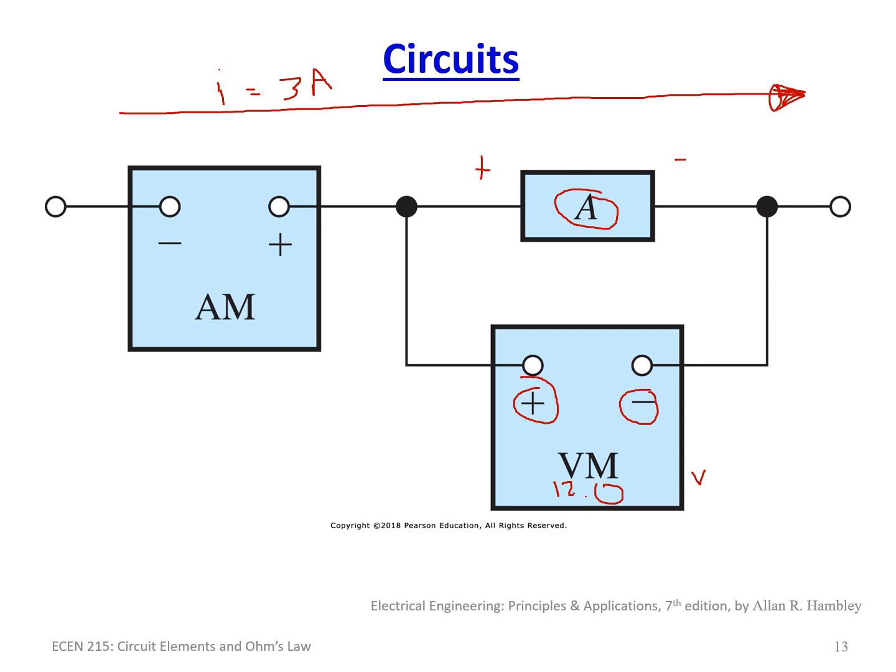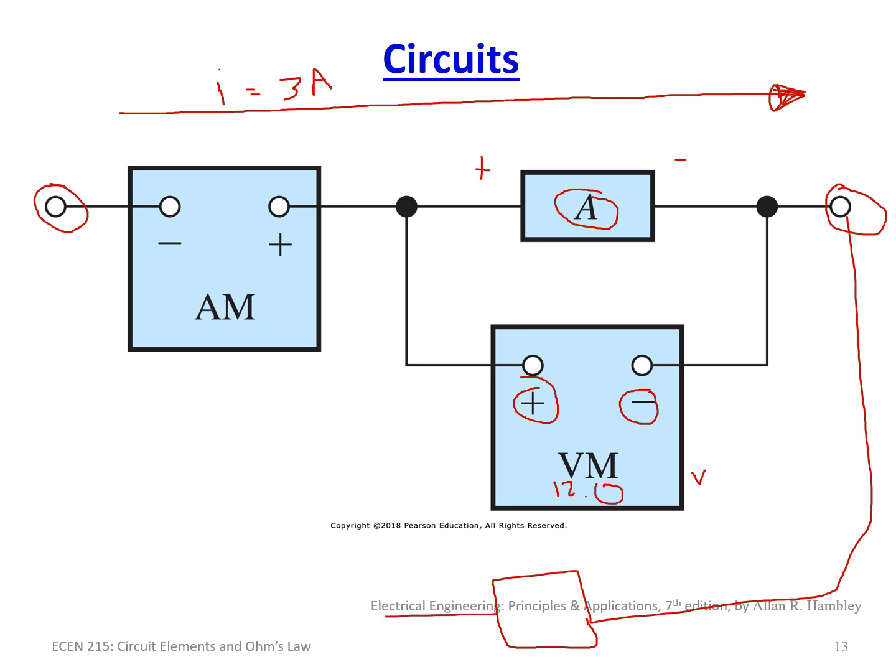If we have 3 amps going through here, through some sort of unknown thing that is connected here, whether a power supply or whatever it may be, there's some other circuit element here that is unknown. We'll just draw it as a box and put a question mark in it for right now. So we have some sort of device, a power supply, driving this current of 3 amps through circuit element A, and we'll pretend A is a resistor. So we have 12 volts going across it, and 3 amps going through it from positive to negative.